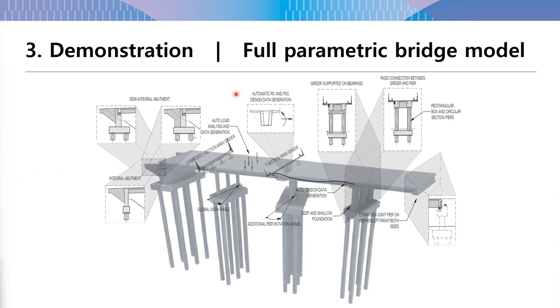The user also has a possibility to define data for pre-stressed concrete and reinforced concrete member design. The user enters longitudinal reinforcement data and shear reinforcement data, and the parametric script automatically generates the input required for MIDAS Civil and MIDAS Civil NX to design these members.